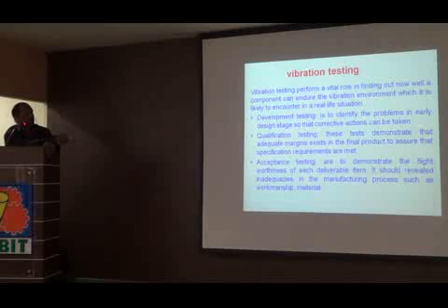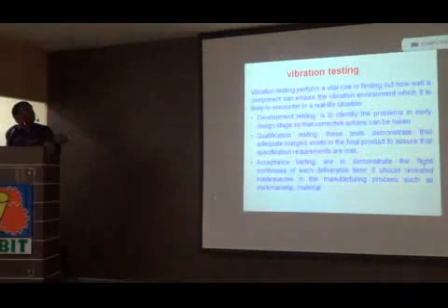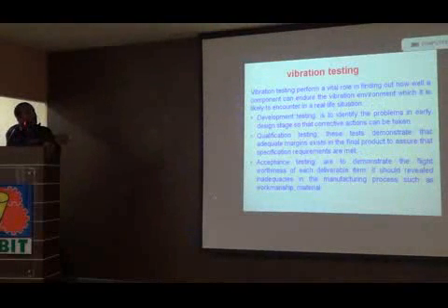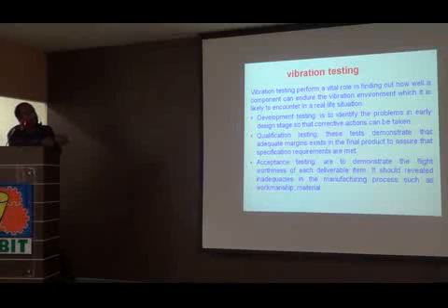Acceptance is another type. Development testing, in the initial stages, is to identify problems in the early design stage so that corrective actions can be taken. In this, we give more levels than the standard specifies, so that any failure is corrected and then we go for redesign. Qualification testing is the test that evaluates after the design is frozen, to demonstrate that adequate margins are there in the final product.